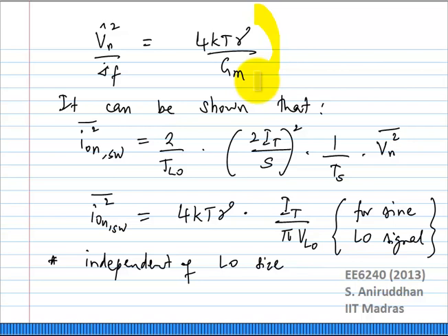But because the pulse widths are much narrower, you are actually sampling more broadband noise. So if you increase the device, you actually have lower input referred noise, but you are pulling in more of the noise. Whereas if you make the device smaller, you are increasing the input referred noise, but since it's switching much slower, you are folding in less of that noise.